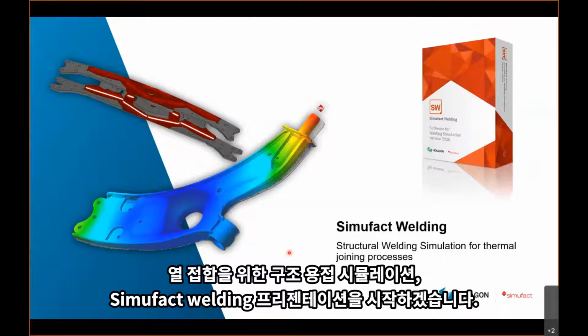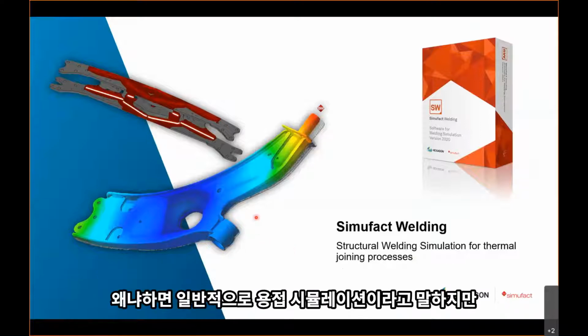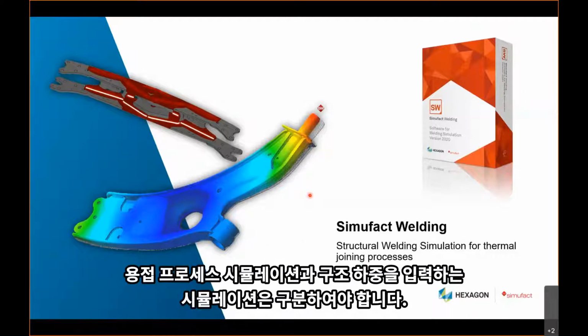Simufact Welding, structural welding simulation for thermal joining processes. This sentence essentially says everything about what Simufact Welding really is and also what it is not, because although these types of simulations are usually termed welding simulation, you have to distinguish between certain aspects of the welding process and what part of it is really going to be simulated with a structural welding simulation.